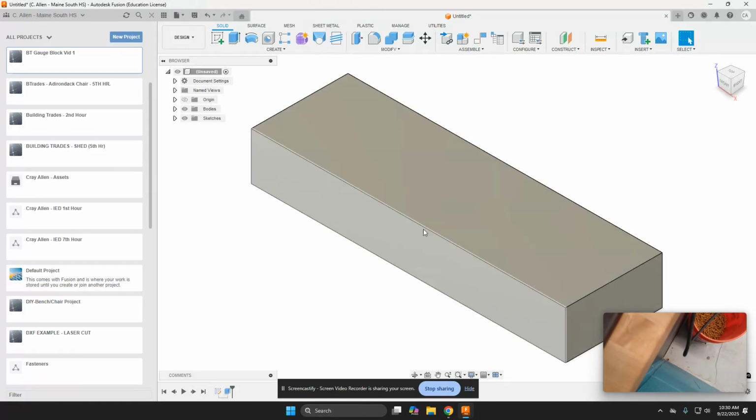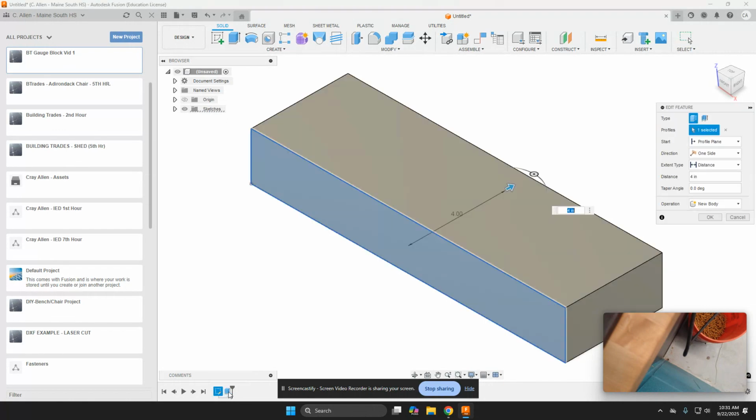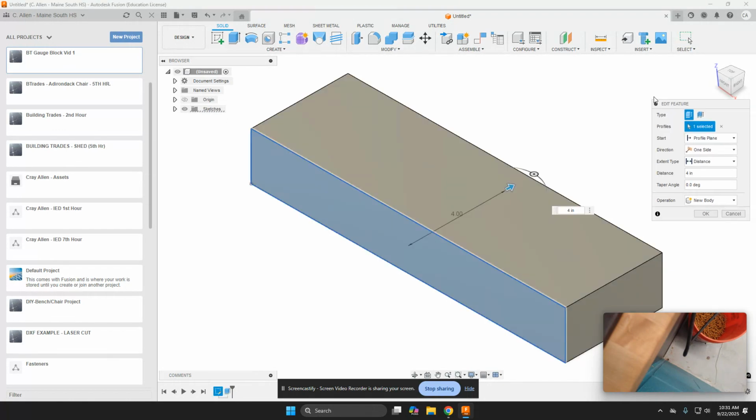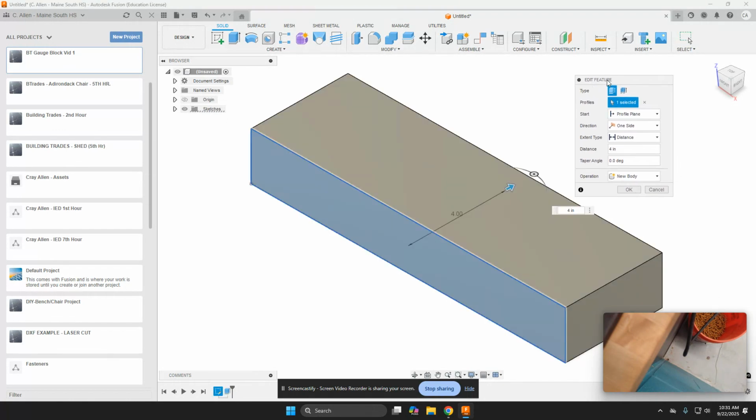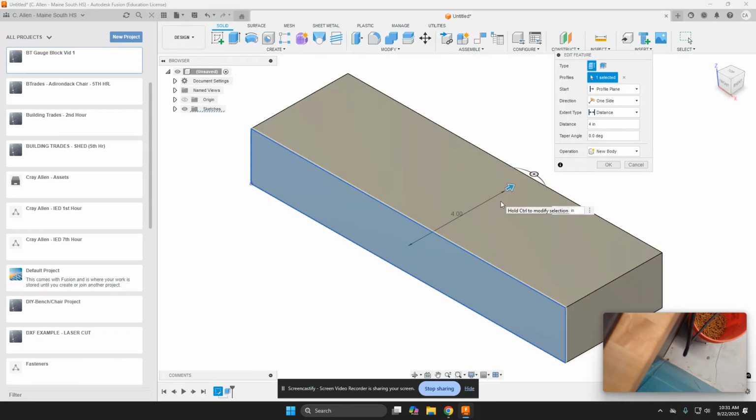So if I want to change that 4 to 3.5, like we just talked about, let's double click on that extrusion piece, the action you just did. Just double click on it in your timeline. It brings up the little heads up display, which talks about editing a feature. When we modeled something, we called it a feature. It tells you the distance, in this case 4. If you were to drag that forward, it would be -4. We went backwards when we extruded our model, so it's positive. Either one's fine, it doesn't matter.